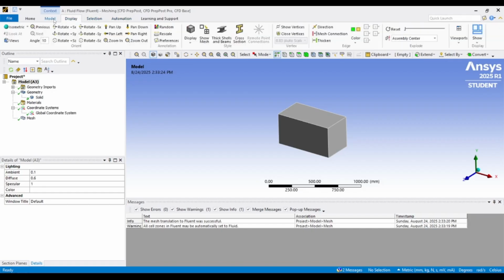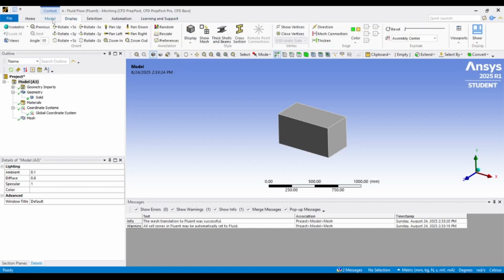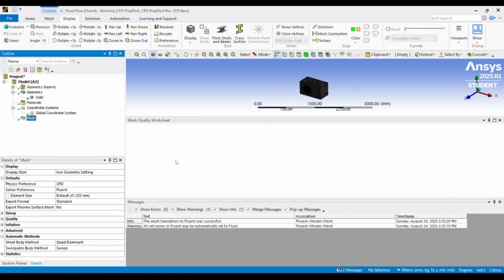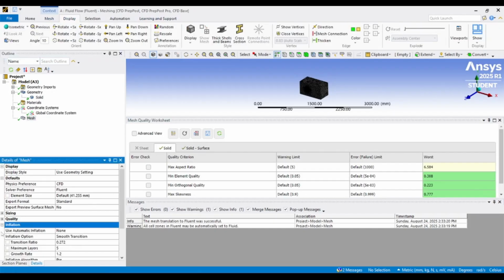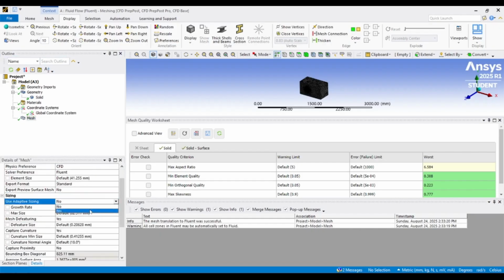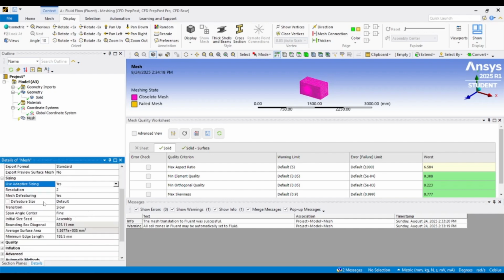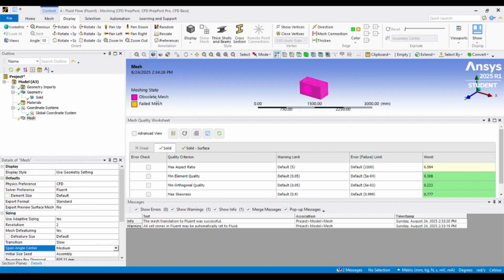If your computer supports parallel processing, use multiple cores in Fluent to speed up the transient run, since this type of simulation is computationally more expensive than steady-state cases. Once the transient simulation begins, you'll notice oscillations developing behind the cylinder. Over time, these oscillations grow into distinct vortices that detach alternately from the upper and lower sides of the cylinder, forming the well-known von Karman vortex street.